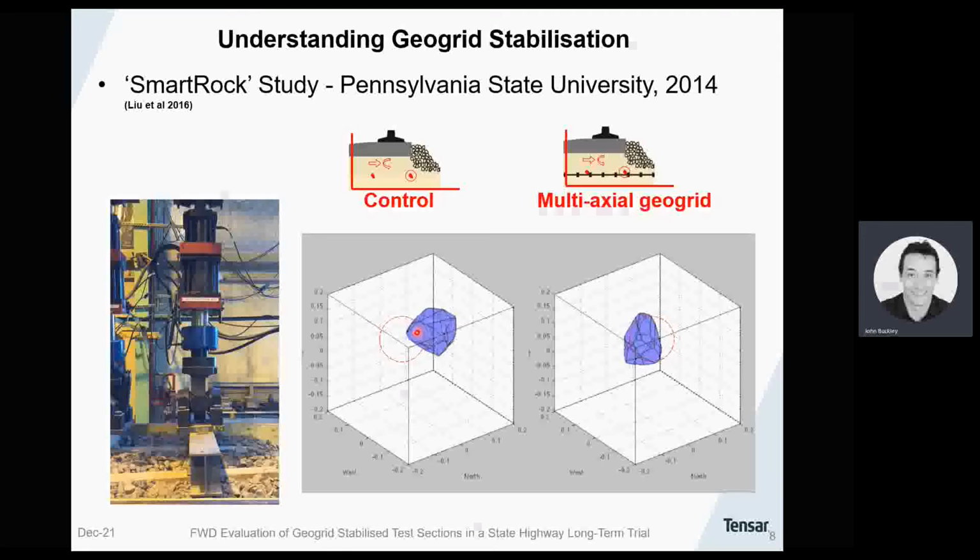So it doesn't exhibit a lot of resilience under this type of loading regime. Whereas the geogrid section is really just staying put, and it hasn't moved out of its original position. It may or may not be interlocked with an aperture, but it doesn't really matter, because if it's not interlocked, it's going to be surrounded by particles on every side that are.